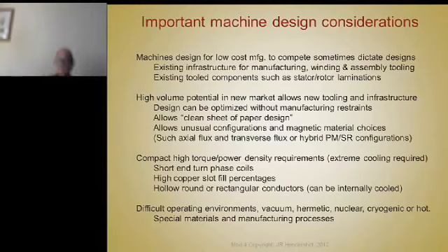So cooling passages are put in between sections of the stator and the rotor core, and fancy pressurized blower systems to blow air. Even large machines use liquid nitrogen, and hydrogen, actually, they use hydrogen cooling.